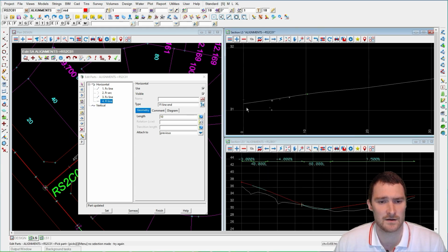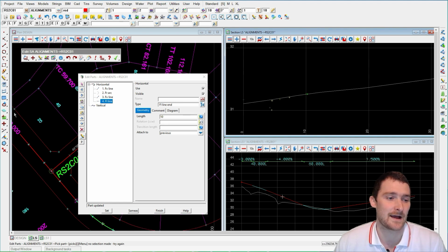So we have a crowned road with a high point in the middle of the road and falling away down to our lip of curb. So for the first length of our vertical geometry, we need to match into both of these points to maintain that crossfall for any car that goes straight through the intersection.